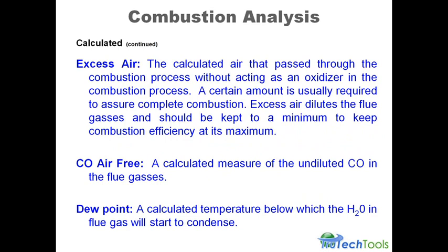CO air free is a calculated measure of the undiluted CO in the flue gases. And this is one of the most important measurements. There are two measurements your analyzer is going to make with CO: one CO and the other one CO air free. The only reason that we look at a raw CO reading on a combustion analyzer is to protect the CO cell. We don't want to overrange the cell.